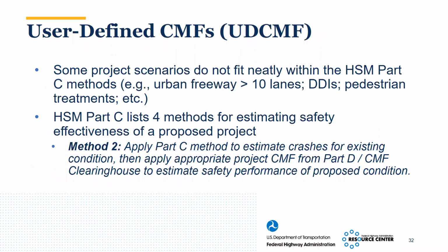So let's talk about user-defined CMFs a little more. What are they and why are they needed? Well, the HSM Part C models cover a wide range of facility types and scenarios, but certainly not all. And in many projects, the scenarios don't fit neatly within the bounds of the HSM Part C method. For instance, the models are only applicable for urban freeways less than or equal to 10 lanes. So if you have a 12-lane facility, technically those models do not apply to that facility. So what do we do?